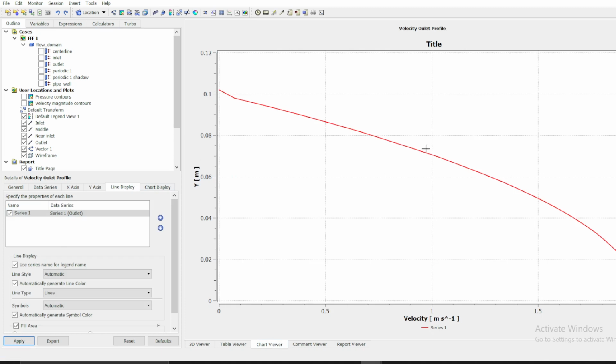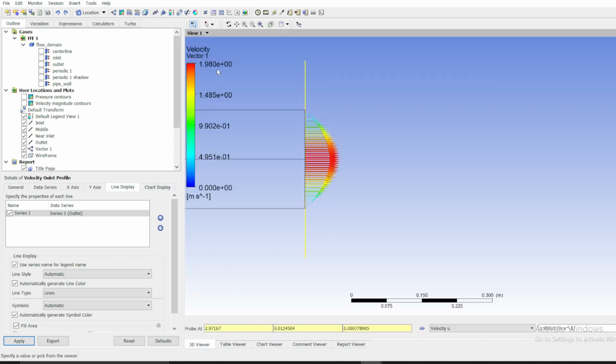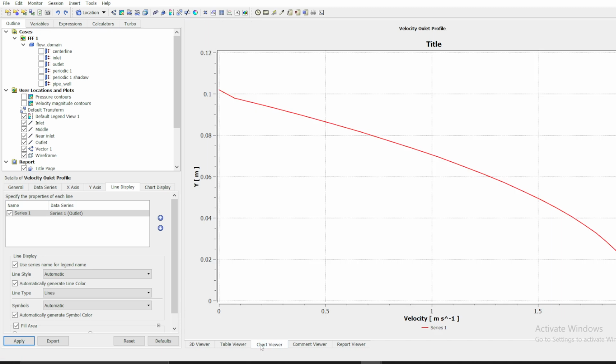You can see now this one is a parabolic one, almost reaching the point of 2, but this value is 1.98, as you can see from the graphics representation. Because of the mesh, if you refine the mesh, remember we used 100 divisions and 10. If you refine the mesh, you might get 1.999 or a value that is closer to 2. And remember the residuals, we used e to power 6. If you increase that value, we also get a more accurate analysis.